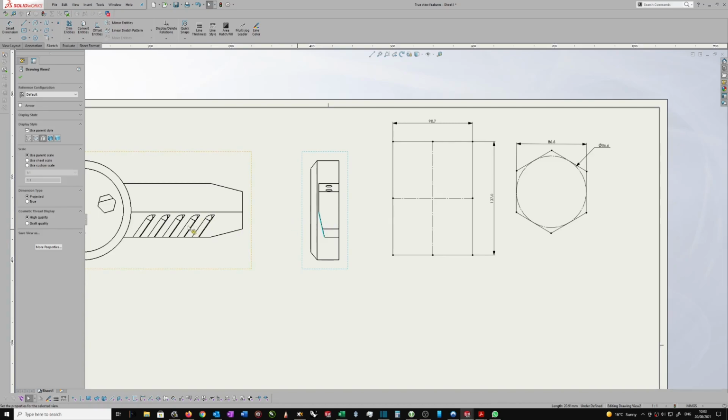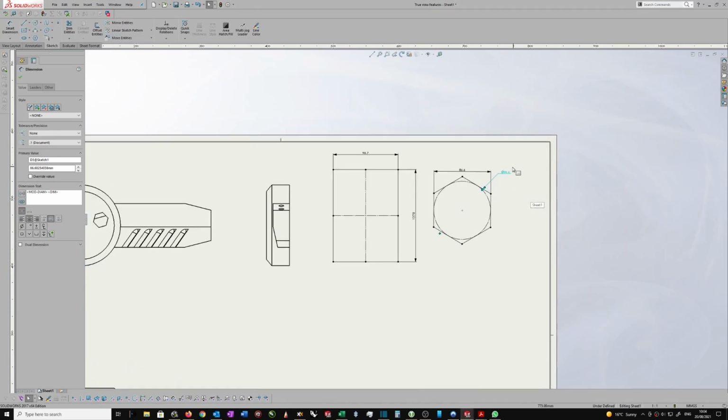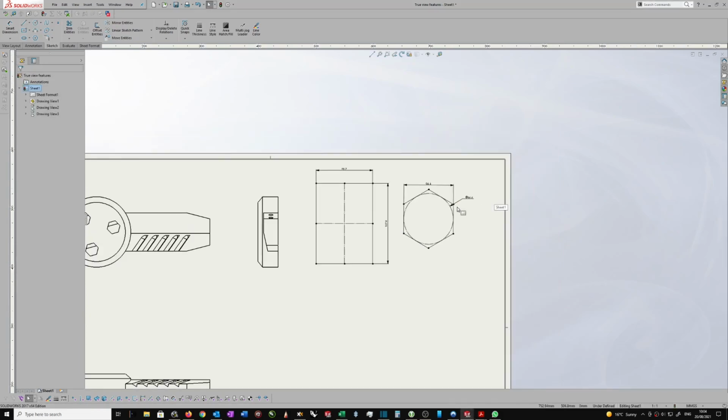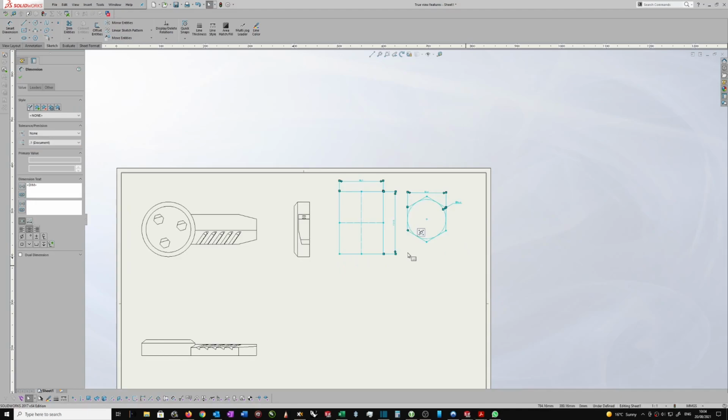You cannot dimension these features inside here unless you've got a point of view which is perpendicular to that plane, and that allows you to do things which are legitimately a matter of parallelism, tangency, perpendicularity, all those rules of dimensioning which are crucial because they entail dimensioning the true shape of the thing, not some sort of representation. And so we'll go through why that's difficult, or why that's a problem now. I'll just try and illustrate it.